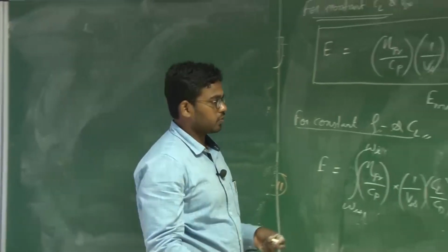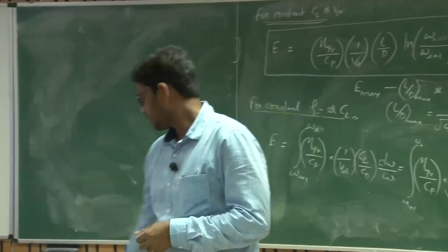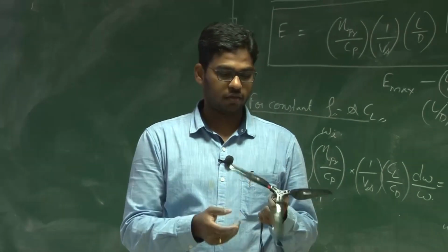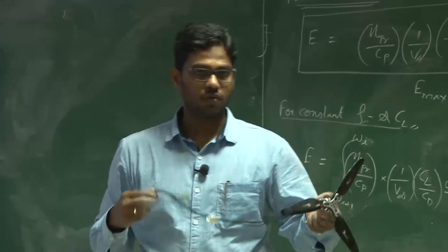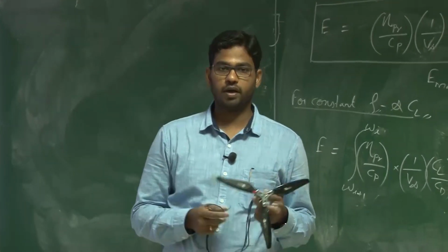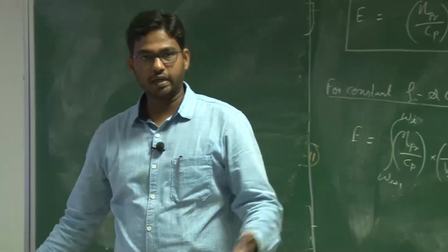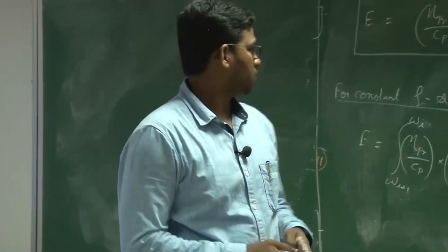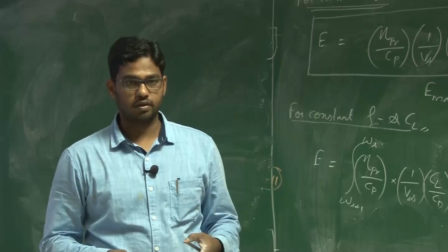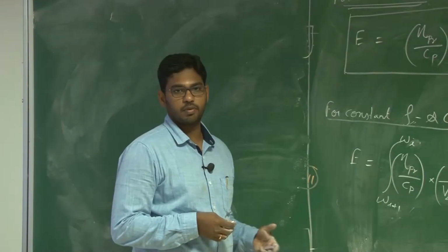Okay. So let us talk about how to estimate the battery weight. Say if you are going for a brushless motor similar to this. If you want to power this brushless motor, you need to carry a battery. Say if you install this motor on a UAV, right? You need to know how much battery I need to carry. Say if I want to have certain mission requirements, say a 10 kilometers range, or an endurance of 1 hour, how does the battery weight change as the mission requirement changes? So let us look at how to estimate the battery weight, right?